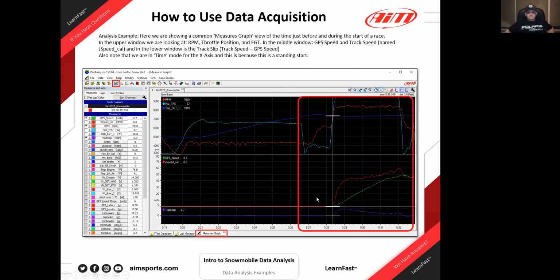Okay, so Jesse, what's the important part about what we're seeing here as far as the data beyond what I've talked about a little bit? I think the biggest thing that you'd want to look at on a start is the pipe temperature, the EGT temperature at the point where he goes full throttle, and then your RPM leading up to that, which would be your engagement. And then once he goes full throttle, your RPMs that go to the right there, how consistent they are, if they go uphill, downhill, and also your track speed versus GPS speed right below that.